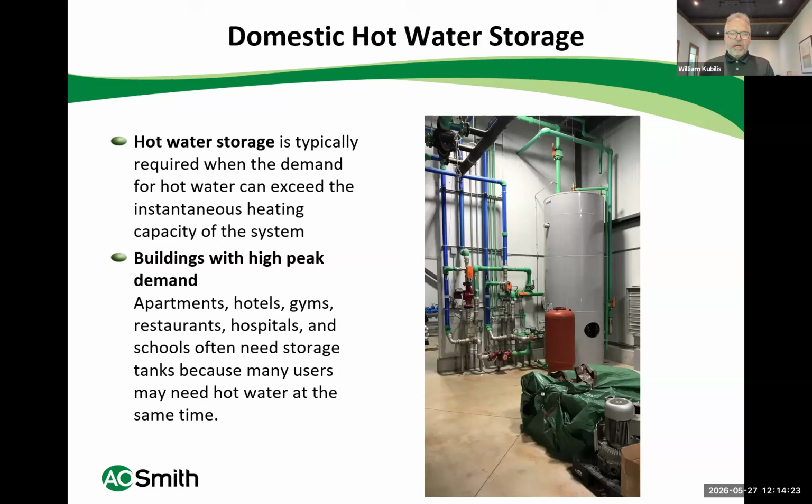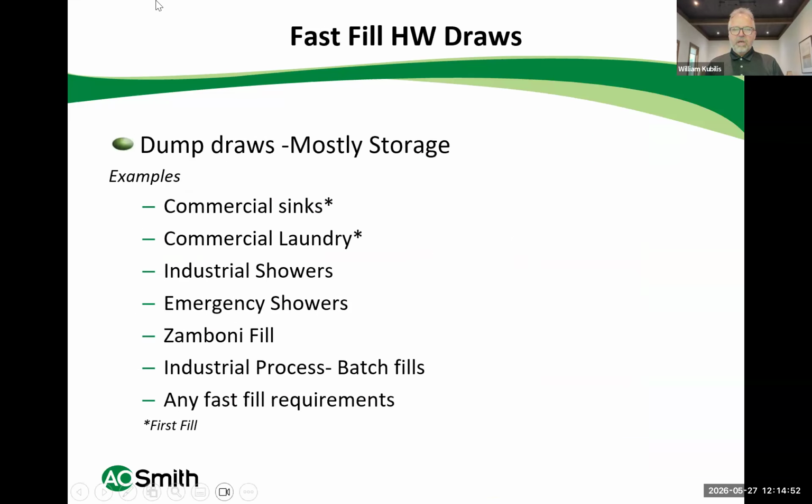Buildings with high peak demand, such as apartments, hotels, gyms, restaurants, hospitals, and schools, often need storage just because of the number of users and the unpredictability of the hot water that's going to be used. Having that storage will help provide the water that can be required for those instantaneous high peak demands.